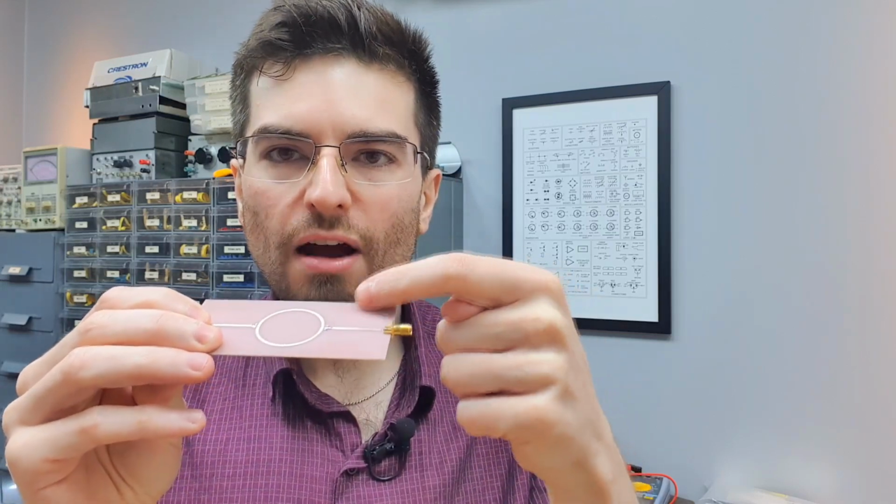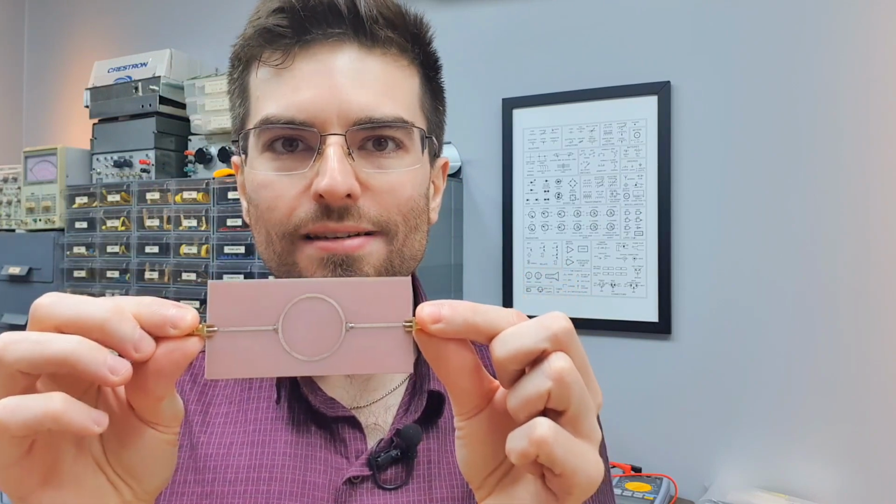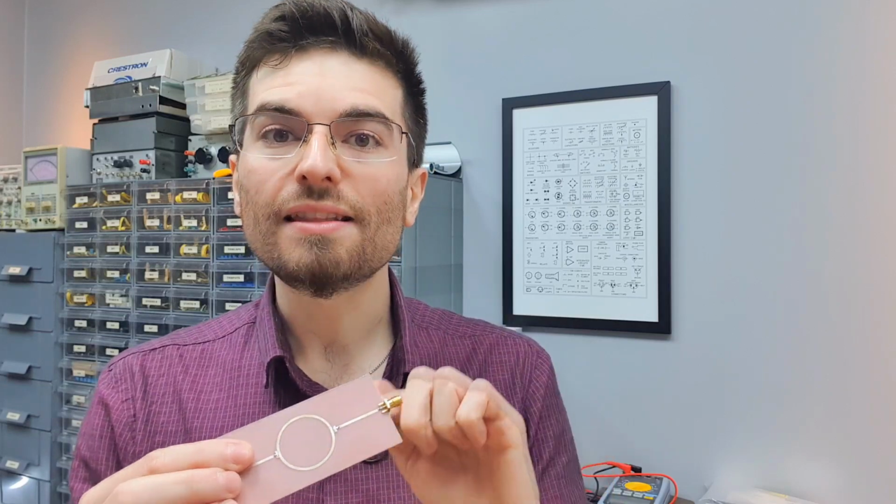They are twisting around here and they are experiencing the relative permittivity of air. So what ends up happening is that for a microstrip geometry like this, we have an effective permittivity that is in between. That makes sense, right? We could conclude this by intuition. We have a permittivity that is in between the air permittivity and the material's.